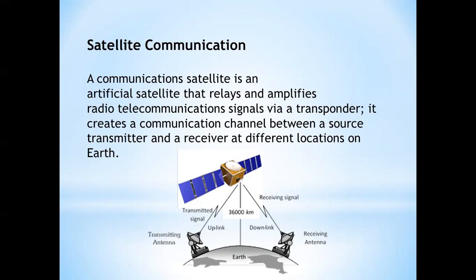The uplink signal received by a transponder is weak and the downlink signal transmitted by the transponder is strong. Therefore, to avoid interference between them, the uplink and downlink frequencies are selected to be different values. The operation of the satellite takes place at very high signal frequencies in the microwave range. The typical band of signal frequencies used by communication satellites are as follows.